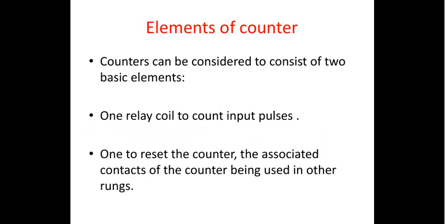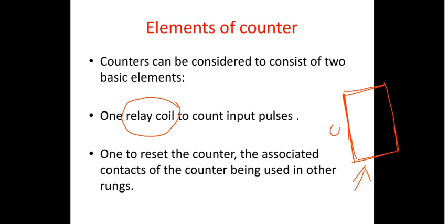So maybe I have got one photo sensor attached to this door, right? Now the moment this person goes inside, the light rays which are being sent from the transmitter to the receiver are cut, and you get a signal something like this. As long as nobody is entering, you would get a straight line something like this. But once a person enters, this is no longer going to remain a straight line. You will get some obstacle, that is called the change in the signal. It can be done with the help of a relay coil also, as far as the PLC is concerned.